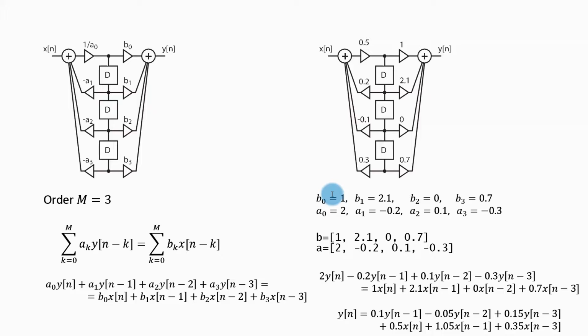If you want to put this into MATLAB, typically you do it like this, and then you can use these vectors for that function filter. And when you just use this general formula and substitute those coefficients, you will get your difference equation. This is a general form of difference equation. If you actually want to implement it somewhere, you need to solve for this output signal. When you do that, you can rewrite the difference equation into this form, and that can actually be implemented.